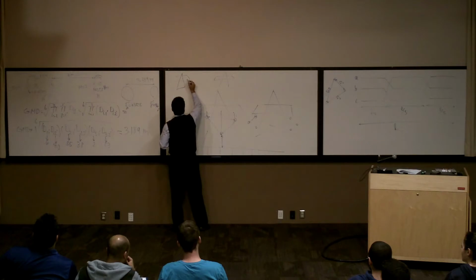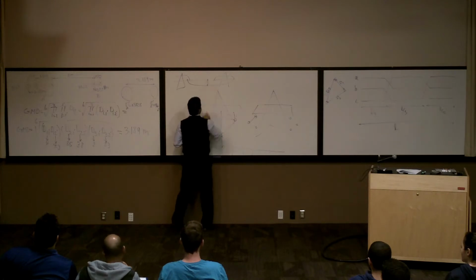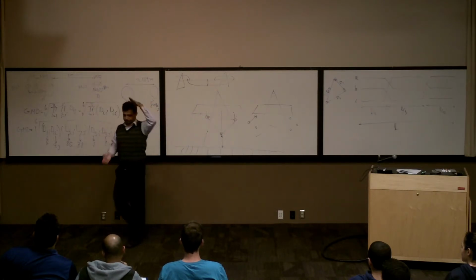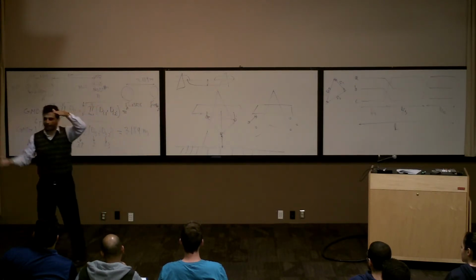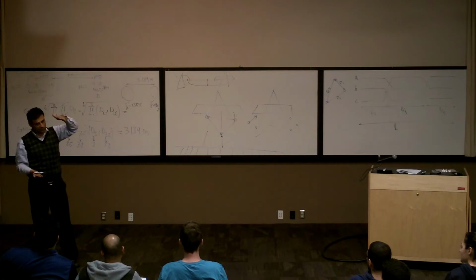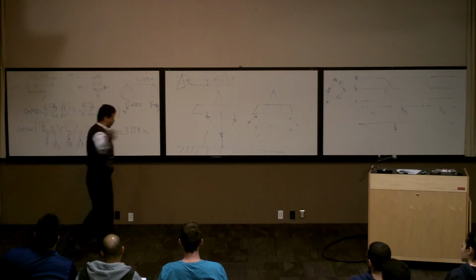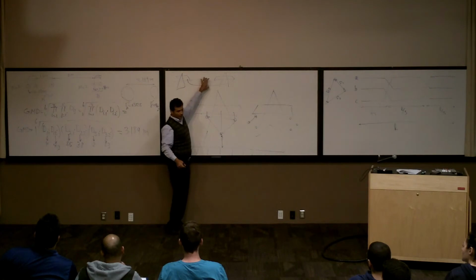So this one comes from here, going here. So this is the minimum, this is the maximum. I don't know what they call it in English, but this is the bend, you know, the maximum bend here. So you should calculate this one for the worst case. Worst case usually happens when? It's hot. Summertime, right? Because the cable is going to be bigger and it's going to be longer. So you have to calculate this one.